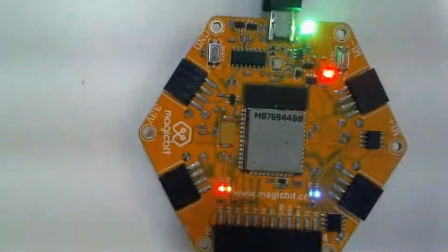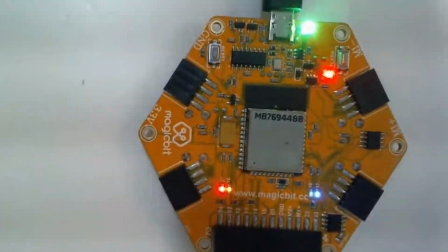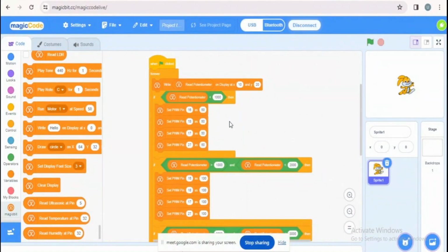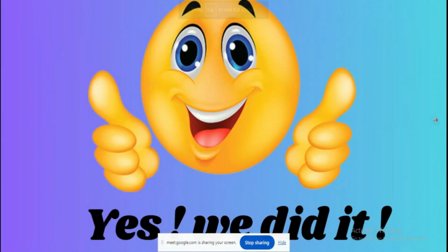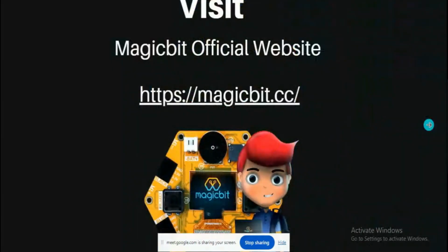Right? Like that, you can change the PWM value in the code from 0 to 255 to change the brightness. So by changing the brightness of the LEDs to different values, not all together, you can change the brightness of LEDs to different values on the same condition. Right? So the variation part is up to you. So yes, we did our light dimmer activity.